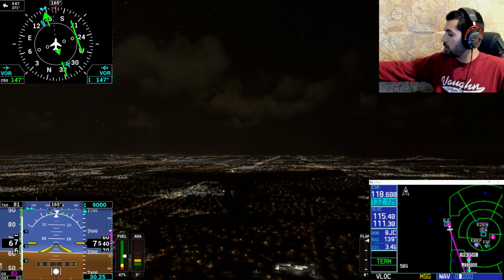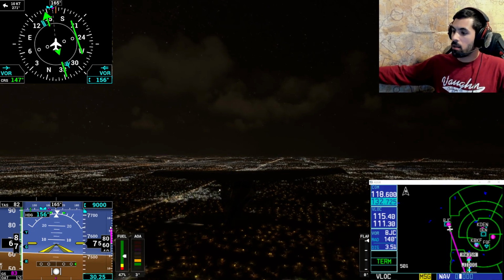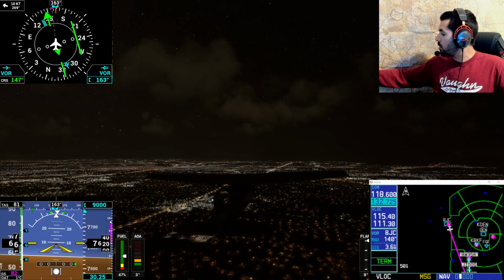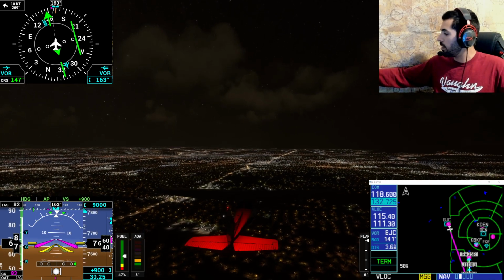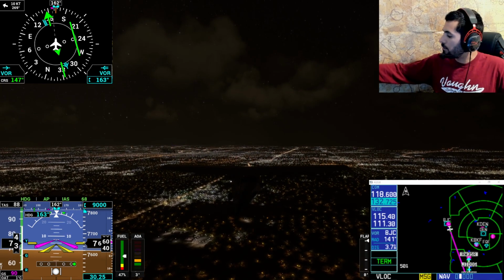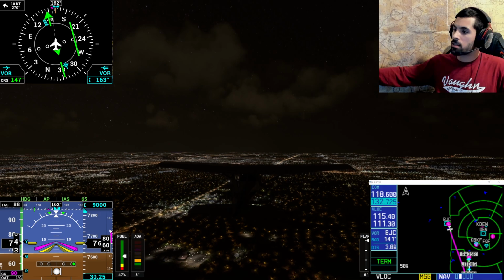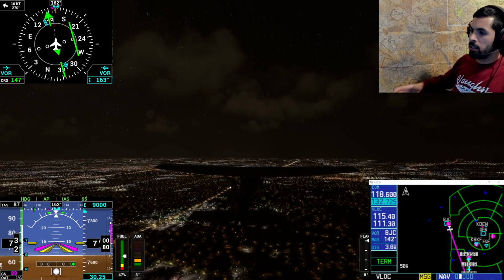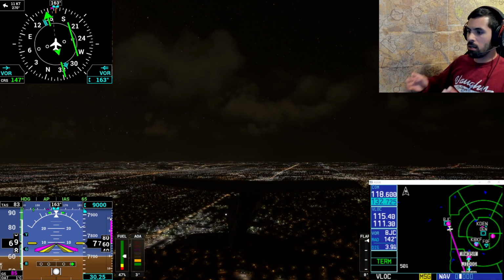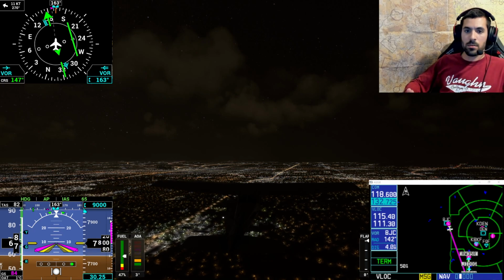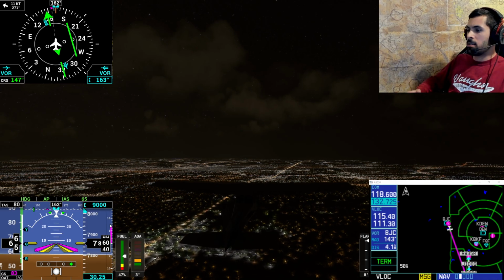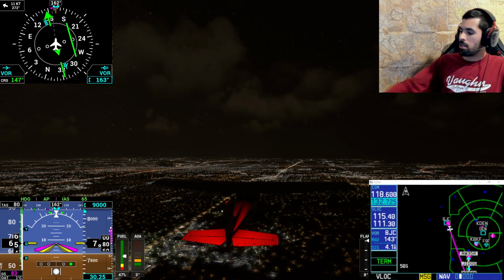Maybe before I set my autopilot, set my heading that I want to keep for now. So I'm going to go autopilot, heading, and then I'm going to choose an indicated airspeed of about 65 knots. Now, once I choose an indicated airspeed of 65 knots and it maintains my heading, now I can just control the direction the aircraft is flying by the heading bug, and it's just going to maintain 65 all the way up until 9,000, which is the altitude I chose.